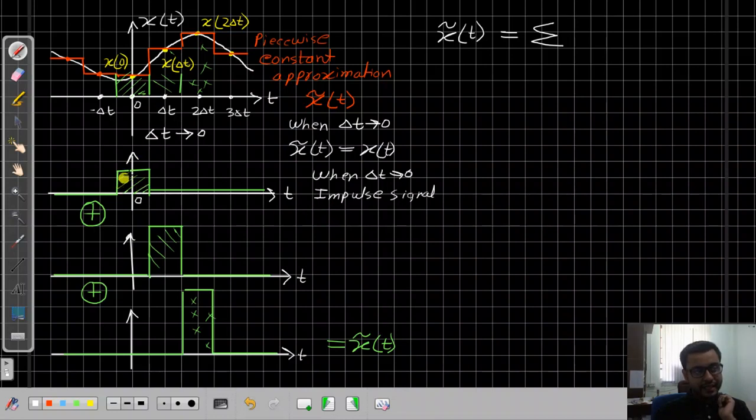However, the area under this curve is not equal to 1, but much smaller, because the height of this signal is not infinite. So it will be an impulse signal but not a unit impulse signal. It will be a much smaller impulse signal, which we shall write as delta(t) multiplied by a very small number, which will represent the area under this curve.